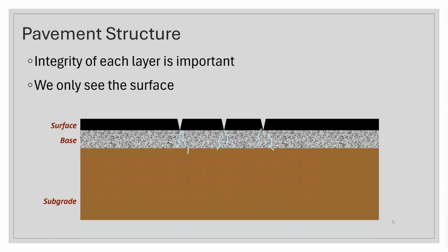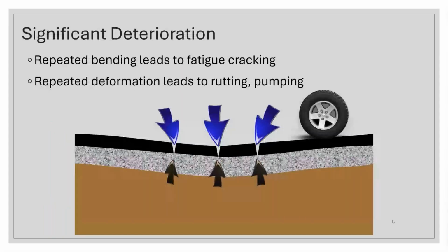So we have moisture that's infiltrating the base, and then as that progresses, that moisture continues to infiltrate into the subgrade, and a wet subgrade is usually a soft subgrade, and if it's soft, it's not giving us the same amount of support that we'd sort of hope to depend on when we design the pavement. So keeping the water out is number one goal. Now, when we have water that gets into the pavement, it's going to create some softness underneath again, from the subgrade. Also, the base can do that. So we have those openings, those avenues for water to come through.